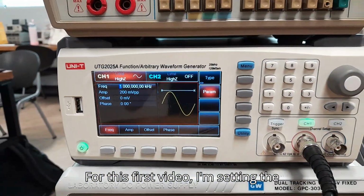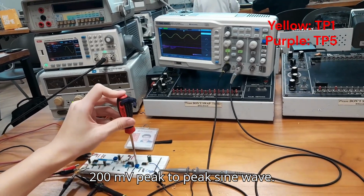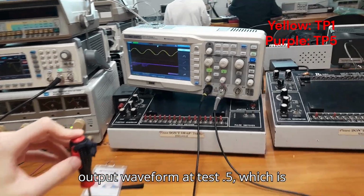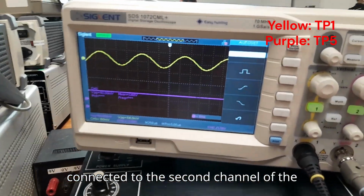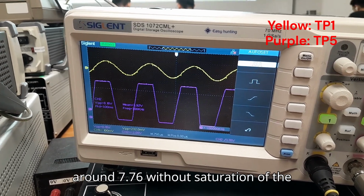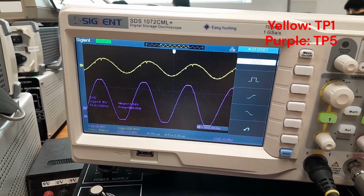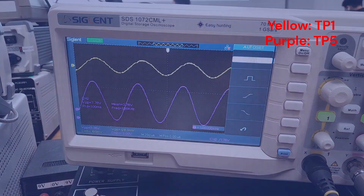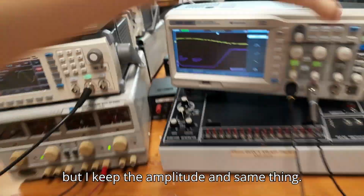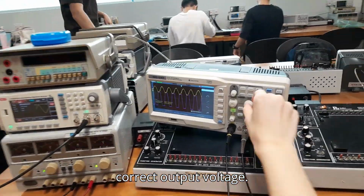For this first video, I'm setting the function generator at a 1 kHz, 200 mV peak-to-peak sine wave. I then use the trimmer to control the output waveform at test point 5, which is connected to the second channel of the oscilloscope. The output voltage obtained here is around 7.76 volts without saturation of the sine wave. Now, I adjust the frequency to 200 Hz, but I keep the amplitude, and same thing, I adjust the trimmers such that I get the correct output voltage.